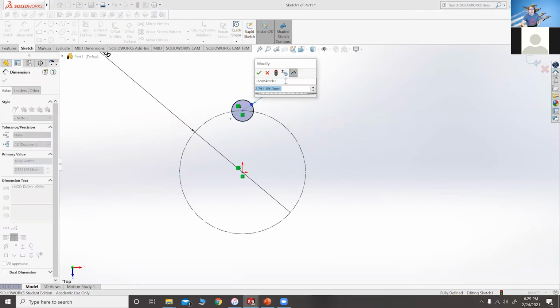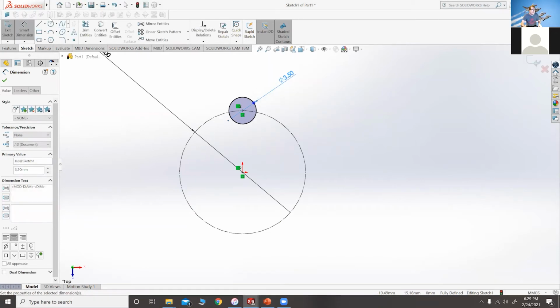So I know those holes, just because I know that motor, are M3 holes, which means they're 3 millimeters. But because the threads are slightly larger than 3 millimeters, it needs a little more. And I don't want to be tapping into this. So we'll go a little higher. We'll go about 3.5 millimeters on this. This can be tuned.